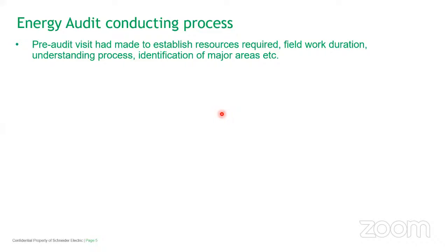It can be a building, a data center, or any industry typically. It can be our own house, for example, if you are doing an audit. So first you need to prepare a checklist. What are the types of energy you are using? Where are the areas you want to do measurements? We should understand how your facility or house operates. What is the operating time of your house? Maybe people wake up at 6 o'clock and sleep at 10 o'clock, for example. So we know the operating hours of your particular facility, house, or industry.